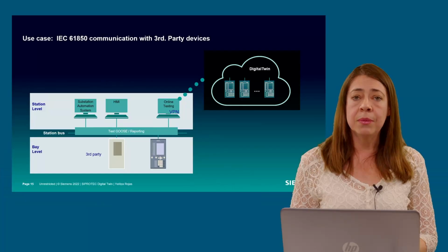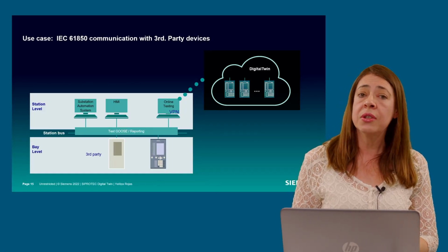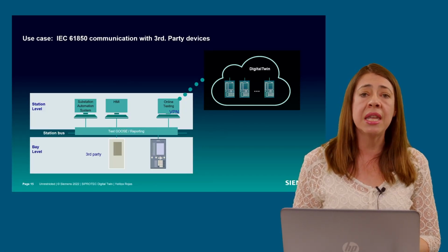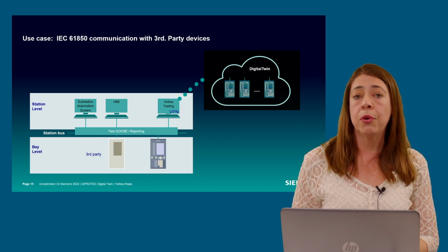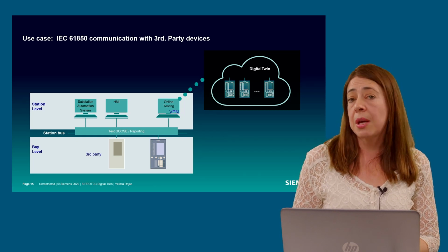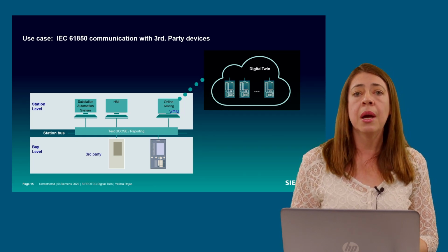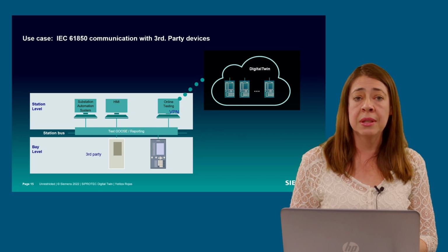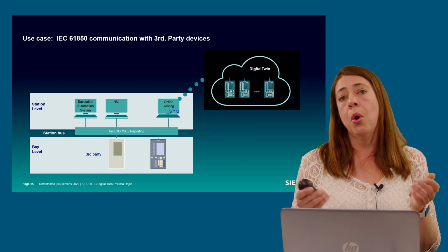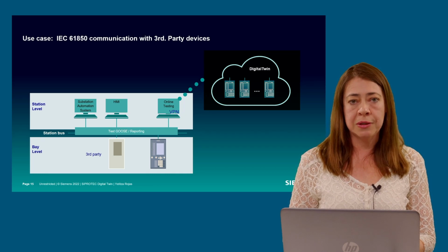With this scheme, you can prove the good communication among IEDs, and the reporting from the virtual device to the substation automation system and human-machine interface, either from Siemens or from other manufacturers.